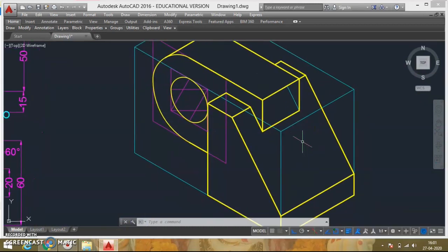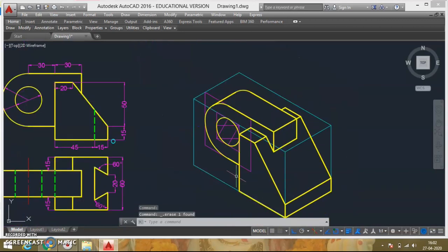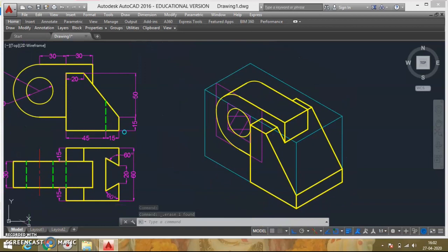Now what you have to do here is actually draw this slot. Now to get this slot, you have to actually draw that slot outside to find out what this distance is going to be. So what you can do is take this as 20 mm, take this angle as 60 degree, take this angle as 60 degree, and draw one parallel line at a distance of 15 mm.